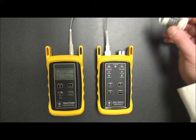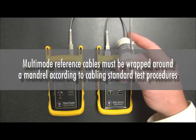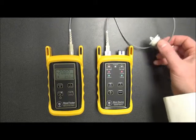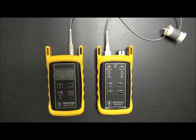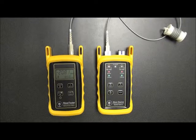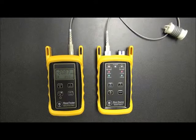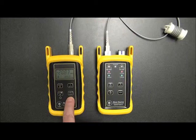Now, I want to note that because this is multimode, we have our reference cable wrapped around a mandrel according to cabling standards and test procedures. And this is something you do only for multimode fibers. Okay, now once we have our equipment checked, we're sure that it's good enough to use for our measurements. What we can do now is set a reference through this mandrel wrapped cable. And this is easily done by simply pressing and holding this unit's 0 button here.